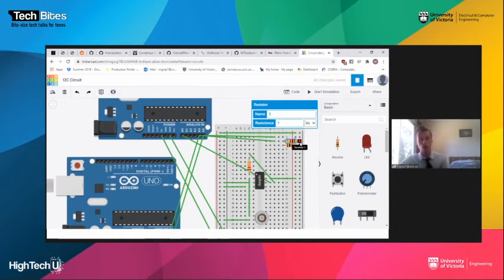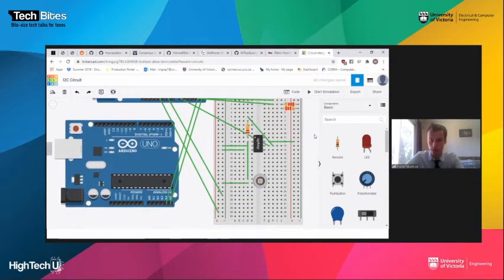And what you put for the resistors determines how much data you can send. So we'll just use about 2K, which usually allows you to send more data, but that won't be relevant because we won't be sending a large amount. What is 2.2? And to make sure that these are the same, connect the grounds.